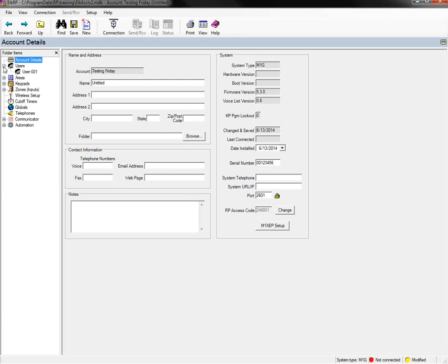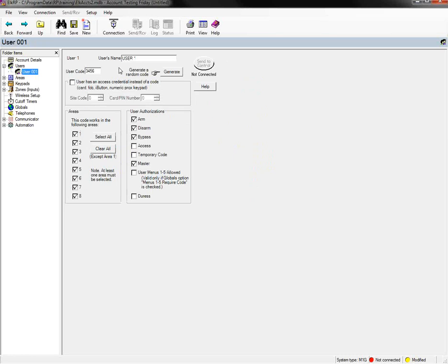Now, we can have up to 199 users on a system. So first of all, I'm going to pick on user number 1. And all I did was go over there and left-click on this, and we're going to pretend that we're programming up Amy. Now, Amy's going to be our master user for this account. She's our master because her master code is actually checked. And currently her default code is 3456.